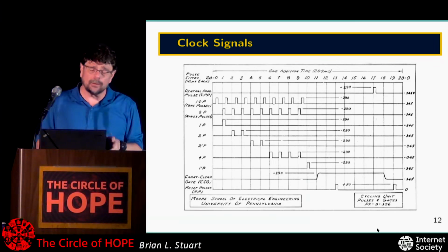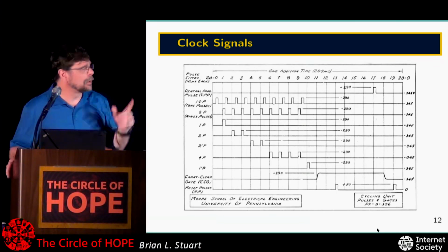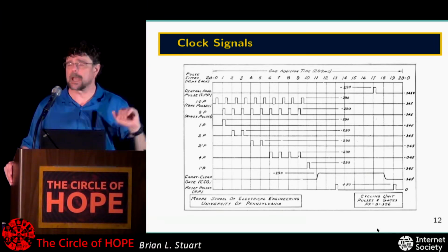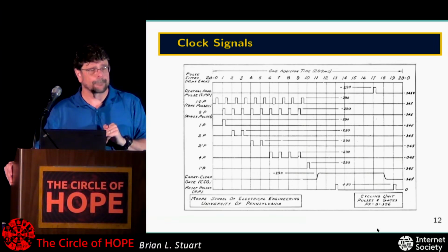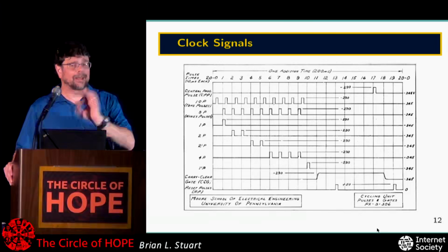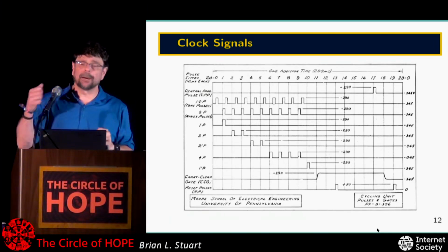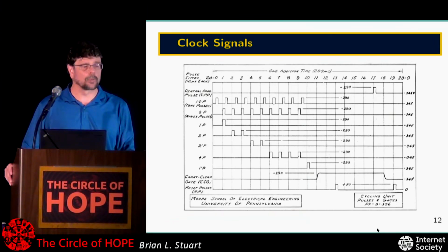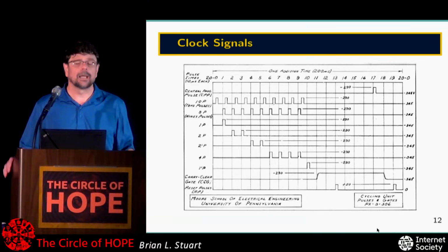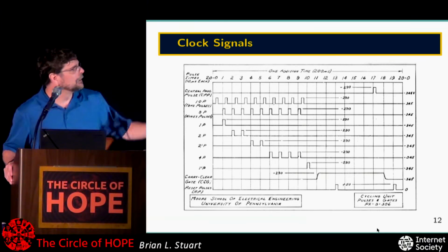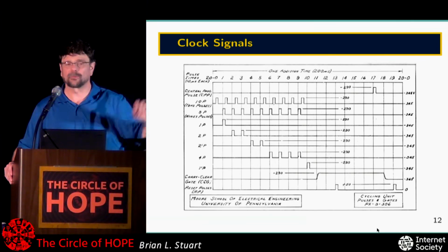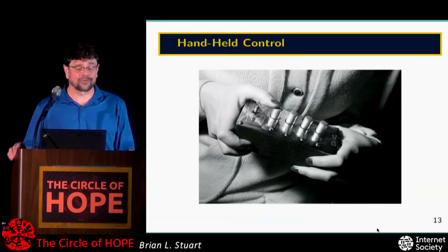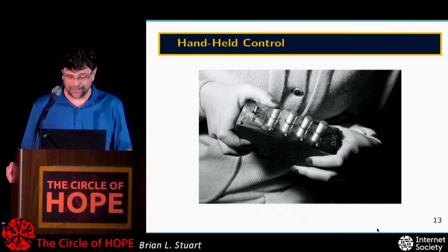But when the clocking was set up in the continuous mode, this would be free running. You would see this sequence happening 5,000 times a second. If you switched it to the 1 add time mode, then you had a button you could push, and that button would do 1 of these screens worth of clocking. And if you switched it to the 1 pulse time mode, it would give 1 of those 20 time slots. So they had planned for single-step debugging at the very beginning.